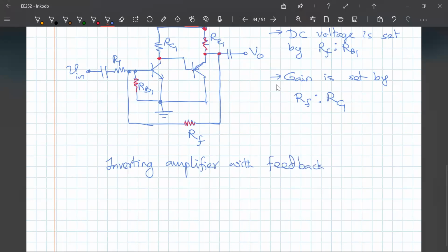because the first one is a common emitter amplifier, which is an inverting amplifier. The second one is a buffer, which doesn't amplify, but the gain will be one, positive one. So therefore, negative gain will be there. Okay, so that's basically what we have as an example. Now let's move on to the feedback amplifier feedback concept.